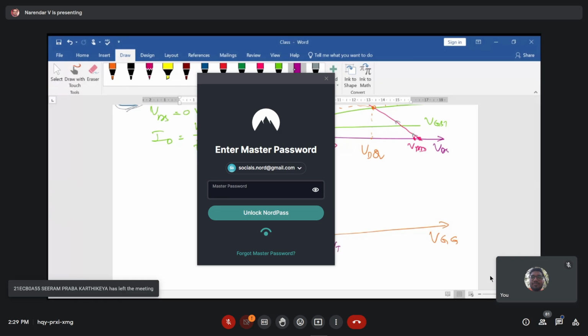When it is less than the threshold voltage, you have the maximum output voltage. Further increment in your VG will bring a variation in your input-output plot. As it goes beyond the VT value, the output starts to drop. You can see a steep transition of output to input, and from this point onwards your transistor reaches the linear region of operation.